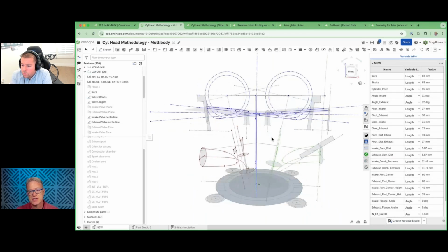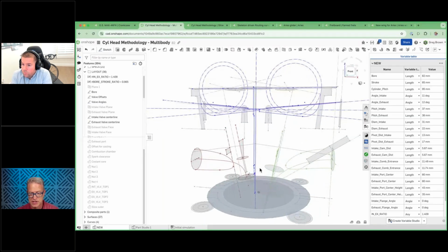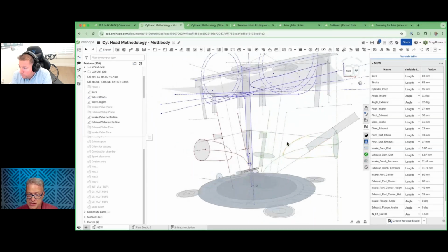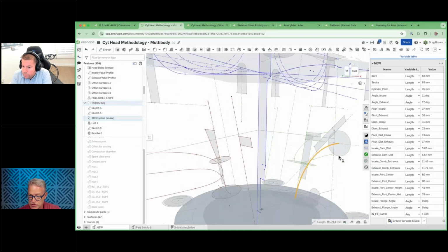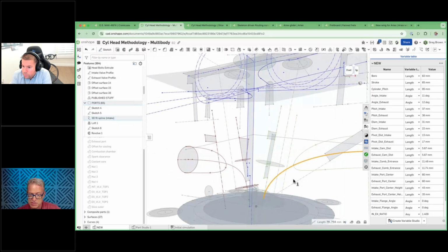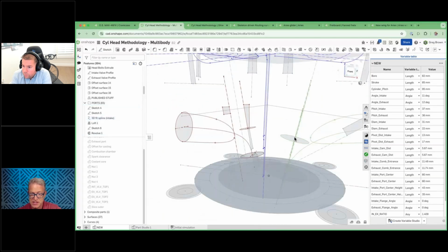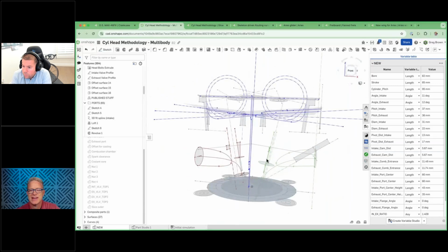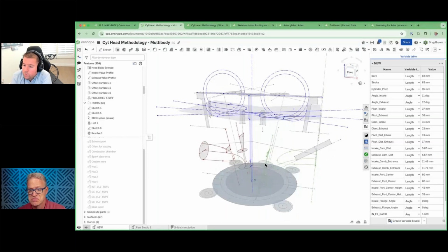With respect to these layout sketches, you can see that I've used colors. Hopefully they show up well for everybody. And I've used colors that are appropriate for my eyes. You can see that on the intake side, everything's green. If I highlight there, you can see this is the intake port spline that I'm using to show the shape of that. So not only have I named it nicely, but I've also colored it. I know that everything green is on the intake side, everything red is on the exhaust side. It's impossible to keep track of so many complicated sketches unless you use some very rigid and diligent scheme for these kinds of things.